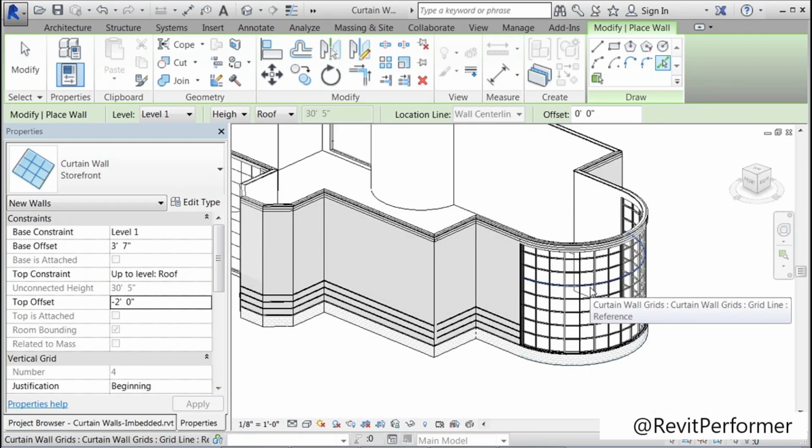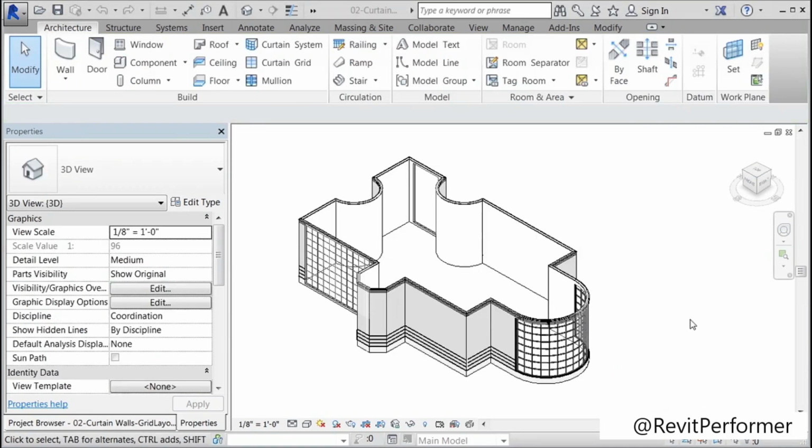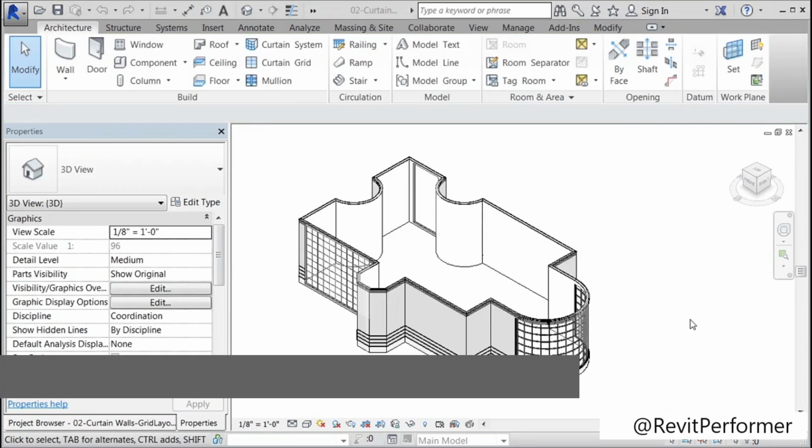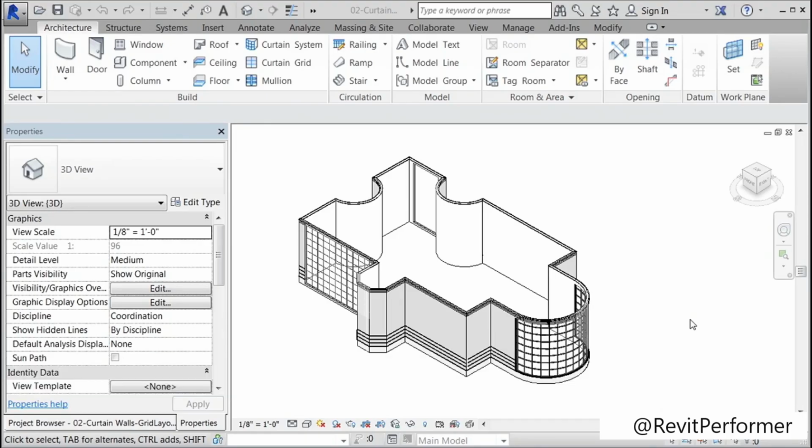do some cool stuff. Once we have a curtain wall in place, we can start manipulating the grid configuration. This can be done with any type of the 3 different curtain walls we've added, but I'd like to use the exterior glazing type. With this video, we'll be adding the exterior glazing type curtain wall. We'll then edit the profile of the wall to have two 45-degree sides. Then we're going to adjust the rotation of the grid to match the 45 degrees we added to the perimeter.